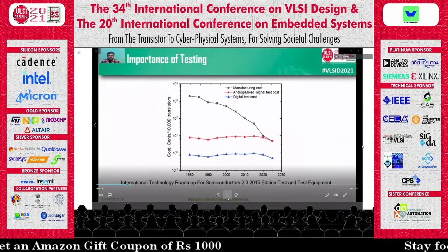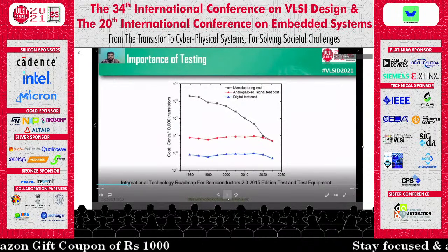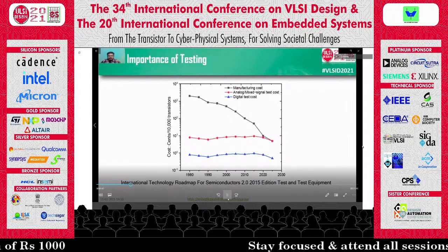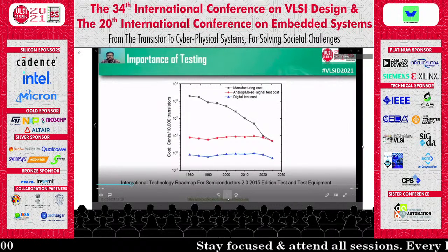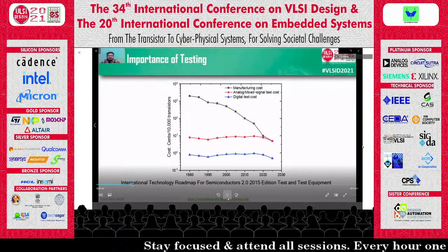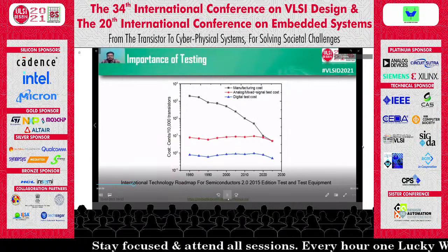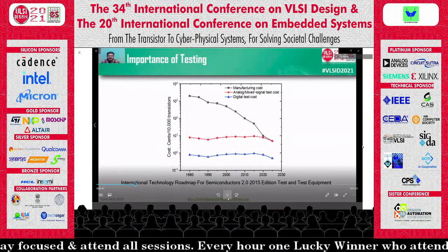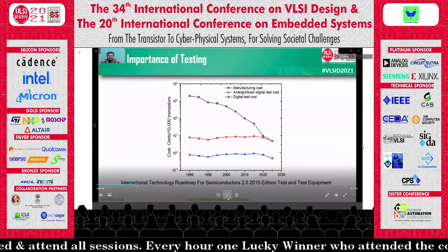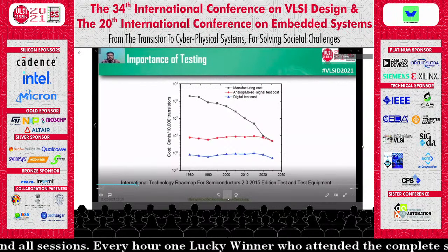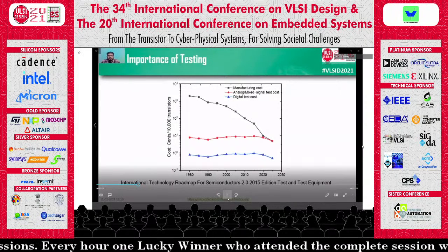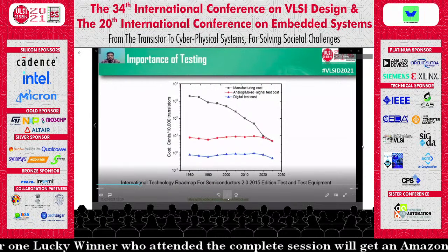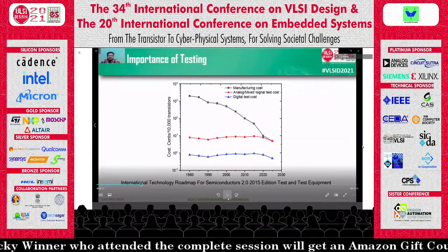Technology scaling over the first few decades has ensured that the manufacturing cost per transistor has decreased steadily. However, the test cost per transistor has not decreased with process advancement. As the number of transistors in an integrated chip continues to increase relentlessly, test cost has emerged as a major showstopper for further advancement. According to the ITRS dataset, test cost is now a major part of the manufacturing cost. Therefore, there is a pressing need to reduce the test cost in high volume chip manufacturing. Also, it is noted that analog test cost per transistor is almost 10 times that of digital test cost per transistor.